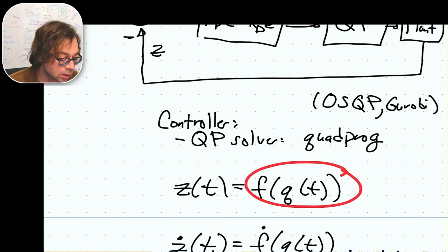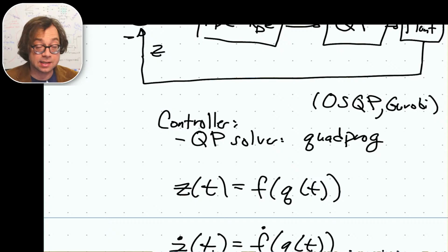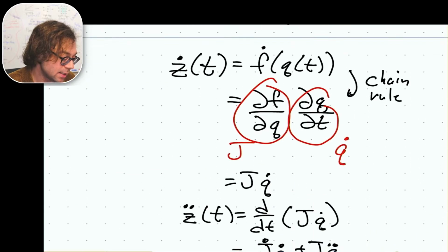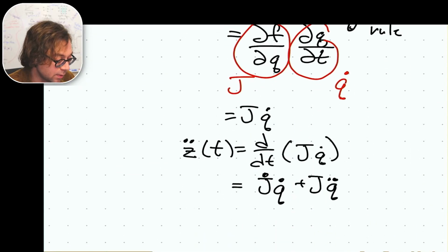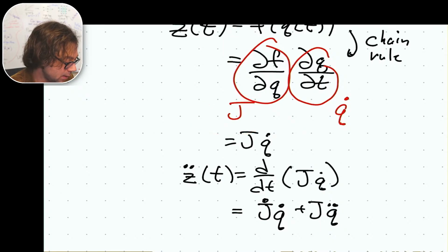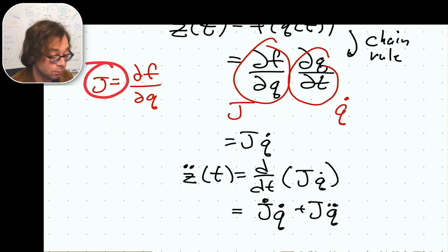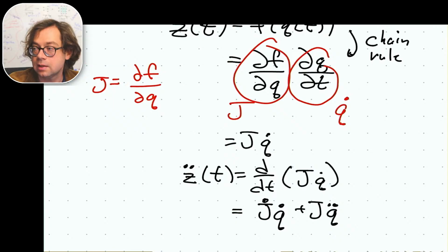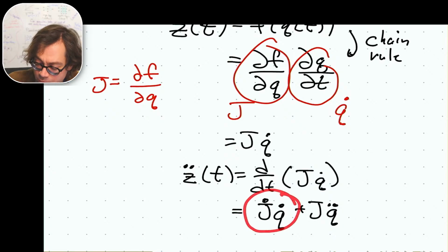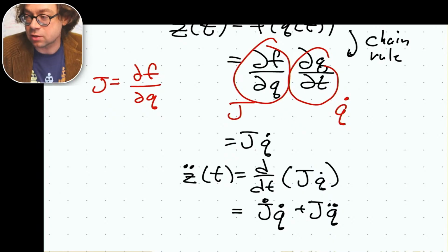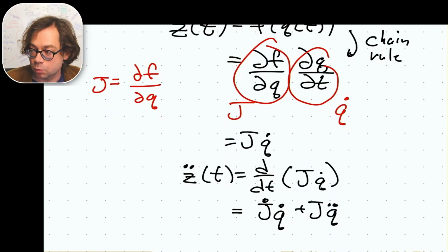We're going to say, hey, what is our task space? We've already written that out. It is the end effector position. We use some trigonometry to figure that out. Not that hard, right? Then we're going to take the Jacobian of that task space to get us J. You know, J specifically in this case is equal to partial f partial q, right? And then we're going to take the time derivative of J. We can do all that stuff, no problem, in the symbolic toolbox. And also we're going to see, can we get away with just ignoring this? We might be able to. We'll see. The time derivative of J is a term that you can often just get rid of, and it's more complicated than you need, but we'll see. All right, back to the code.